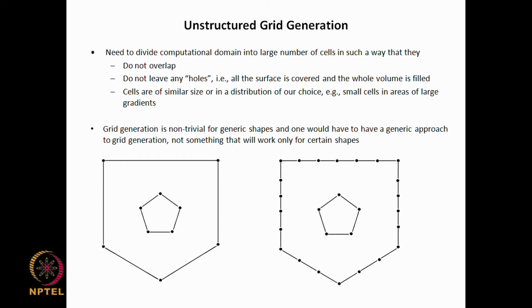So you should want to have a decent number of grid points. Based on, for example, if this is the flow domain shape and if I am expecting some profile here, then I would like to have maybe 10 points in between. Okay. So if I am looking at 10 points, based on that I can say that I would like to have a grid spacing of so much.